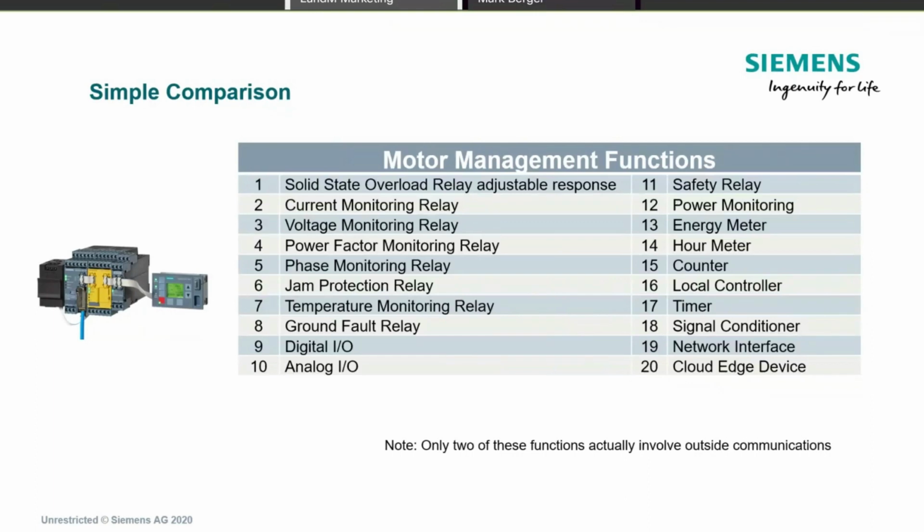And that heat is not good for motors, nor is it good for gearboxes. Put an RTD on the gearbox and have an external fault that could trip the process that you're using, and let the operators know that it's not the motor that is bad. Overload is fine, but the process that you're turning has a problem, such as a gearbox, or maybe a head pulley on a conveyor belt, or something otherwise, such as a pillow block bearing.